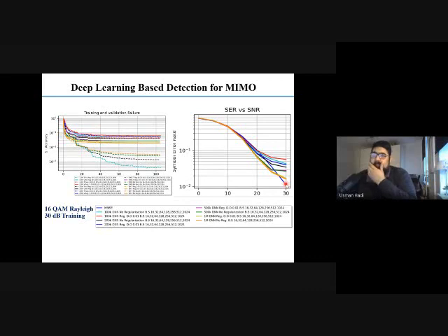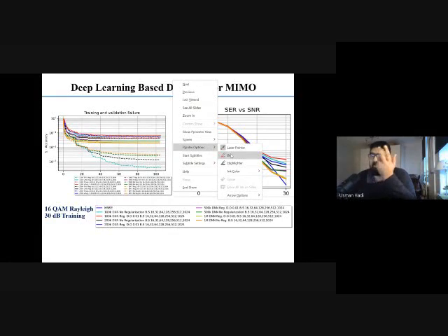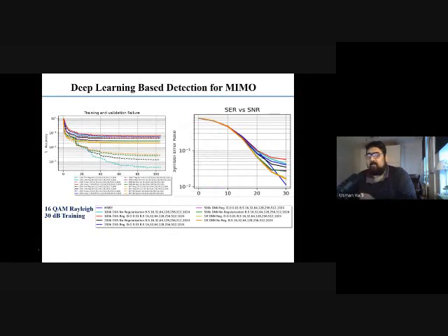That is true, but there is one thing that needs to be understood: the output in this classification system that we have built is a classification type. So you have m to the power of n as an output. If you have 2 receiver antennas, 2 RX, and m is the number of QAM, imagine that you have 16 to the power 2, that is 256 classifications, or a 256 one-hot encoding vector.